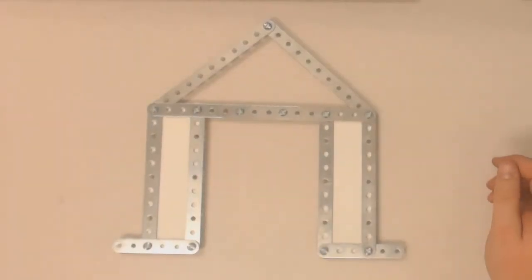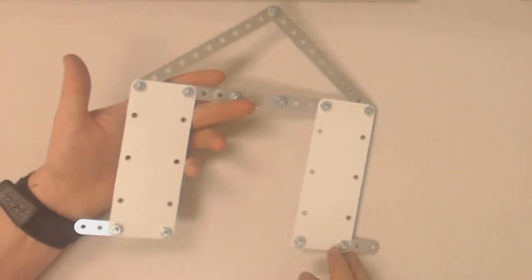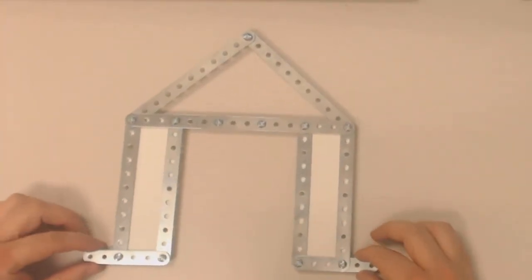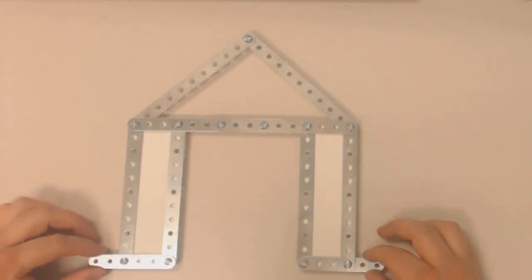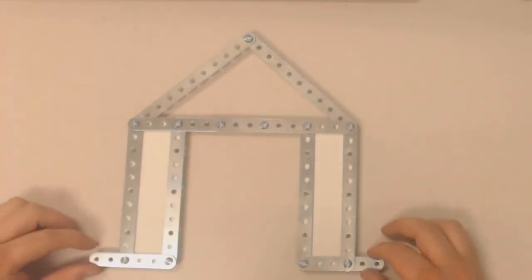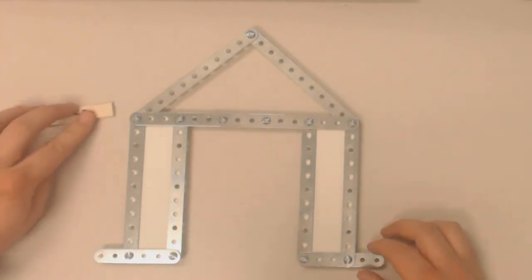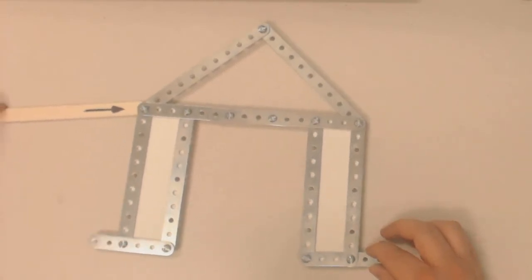Here's our house with our garage door again. And what I've done here, instead of adding diagonal members, cross bracing, is I've added some shear walls, some shear reinforcement to it. And so what this illustrates is the same exact thing structurally. These resist lateral movement, and they do so in a very similar way as cross bracing does. Because if we're going to apply a load laterally this way, the whole thing wants to rack